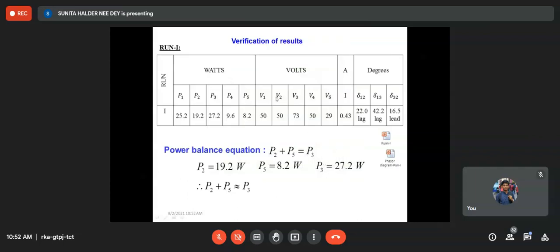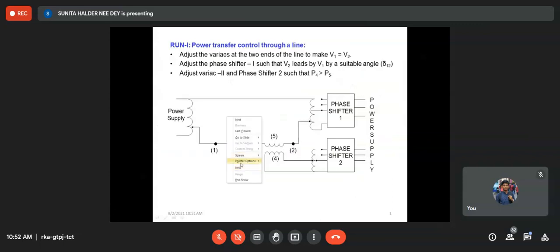Firstly, here current is there. What is current actually? Current is flowing through the line. For current, there is no phase angle meter. But this line is creating the voltage drop V13. So with V13, what will be the phase of the current? It will be 90 degrees lagging from there, is it not? Because V13 is jIX. Understood or not? Yes, ma'am. So in this way, you have to draw the current phasor also.